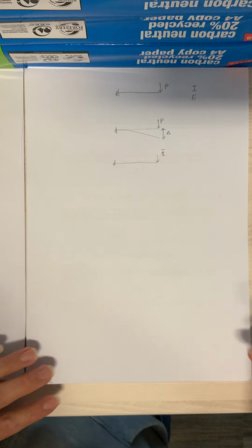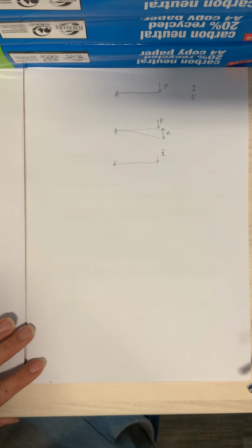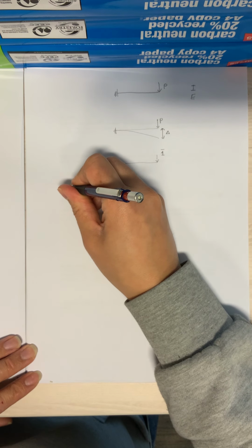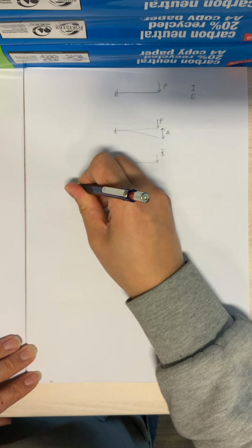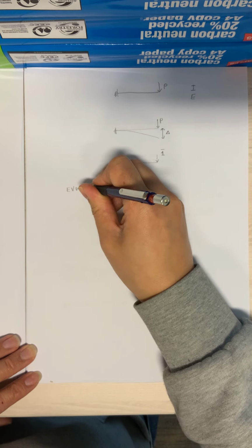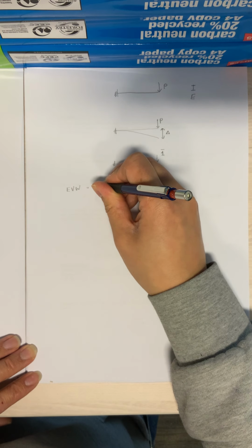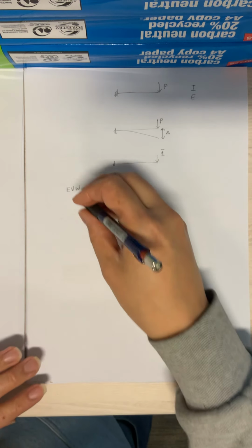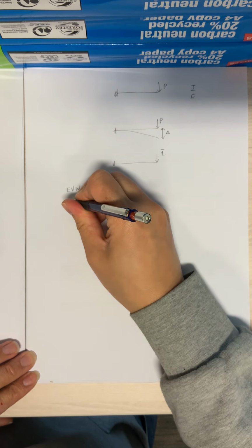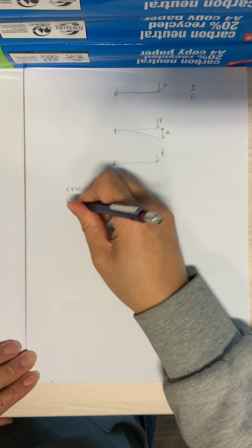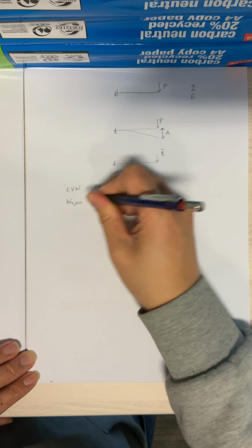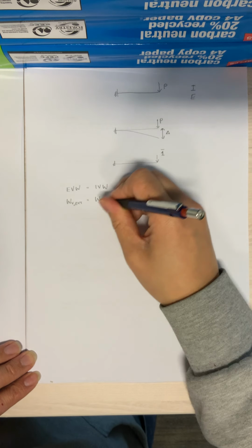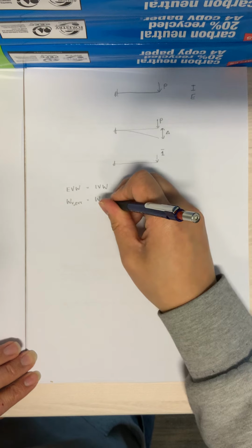So again, we come up with the theorem of virtual work, or the unit load method, and we would say external virtual work is going to be equal to the internal virtual work. Okay, so that would be the first equation that you write, and then we would set that up in the notation as W V ext, for the external virtual work, being consistent with the course book, is equal to W V int.